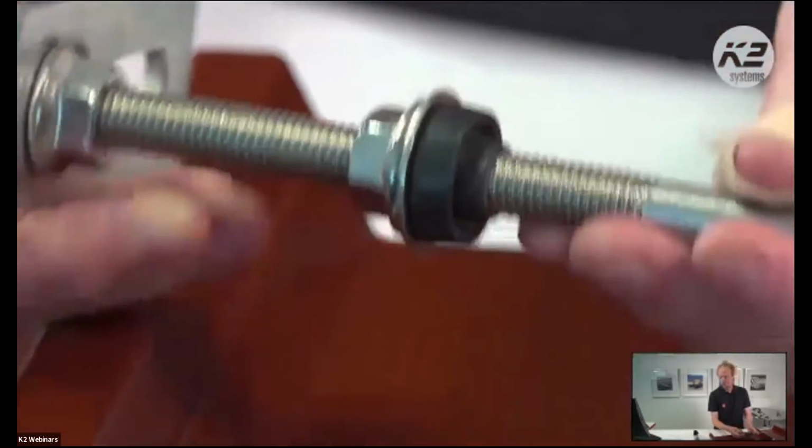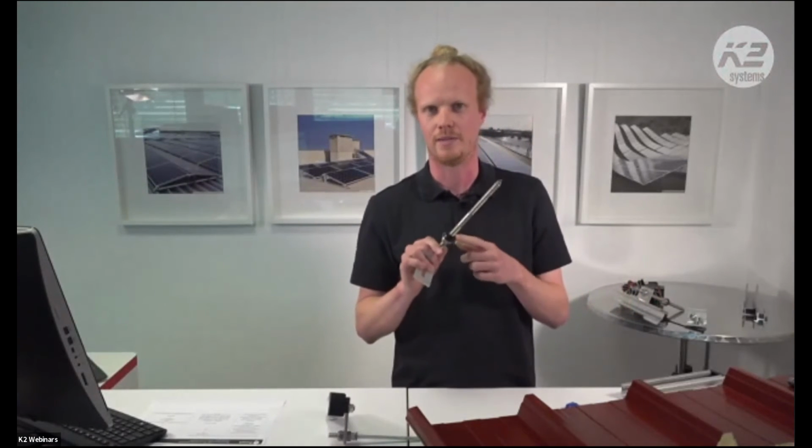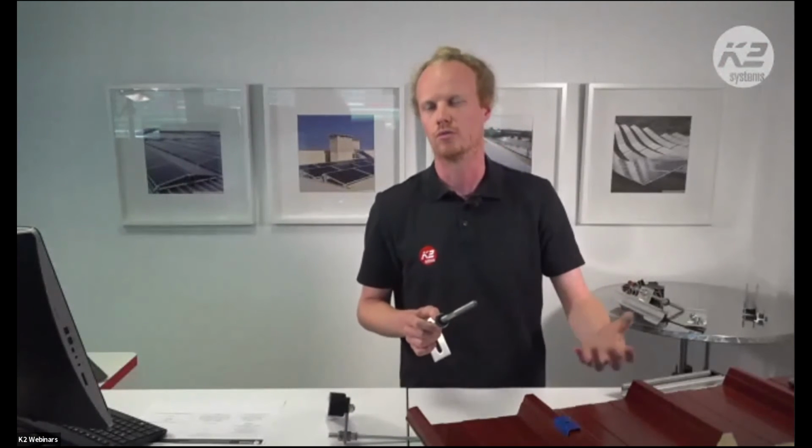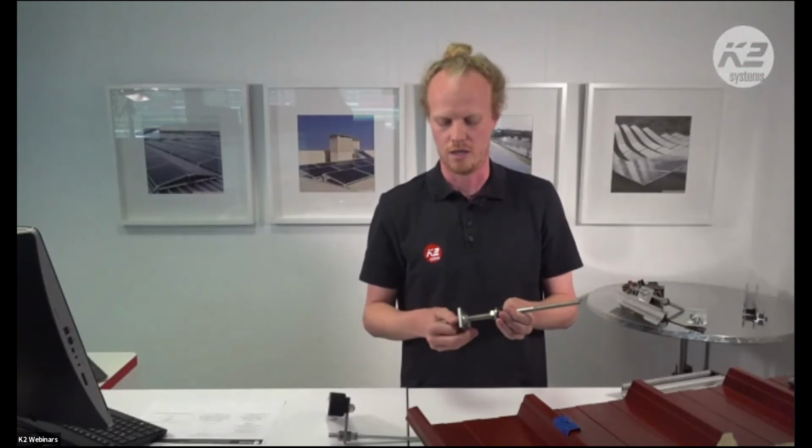This is important because, generally speaking, you really don't want water in your roof. So both options, either the plug sealing we have here or the calotte sealing, ensure that no water will get into the insulation or through the roof into the material, for example the wooden subconstruction or the steel subconstruction as well.